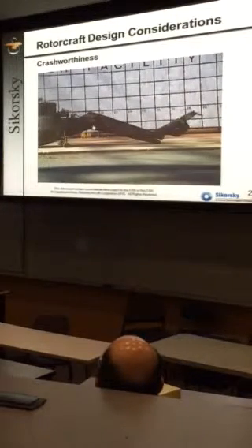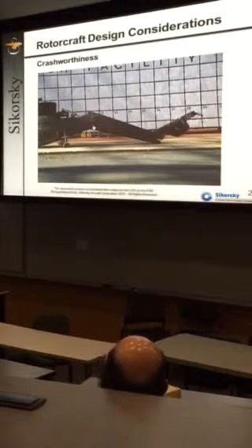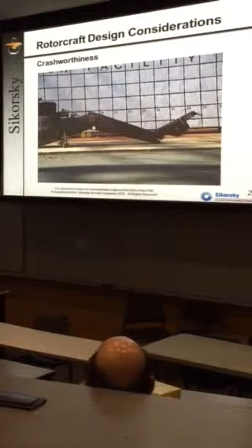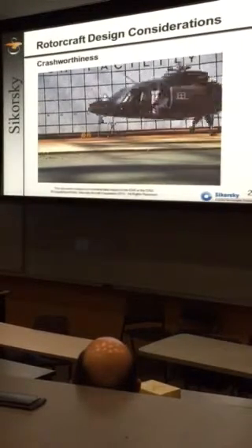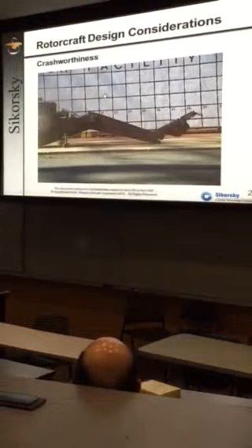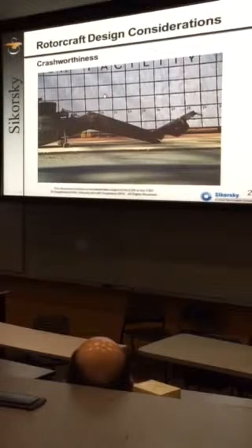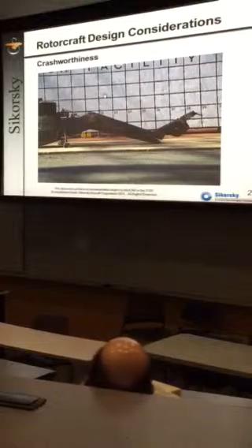where we literally, this was done at NASA, this was an all-composite aircraft, and part of the features of that aircraft incorporate, and Dr. Arabi and I were having this discussion as we were coming over here, when you design for crash, are you designing for the vehicle to survive? No, you're actually designing for the occupants to survive. So you're using the vehicle to absorb that energy. So the breaking off of the tail cone, the stroking of the landing gear, the crushed tub underneath the cockpit area are all designed to absorb that energy so the occupants will survive.